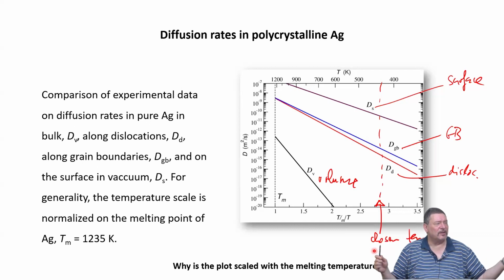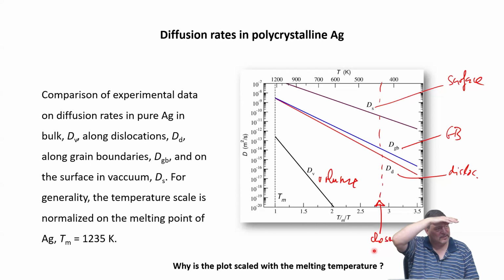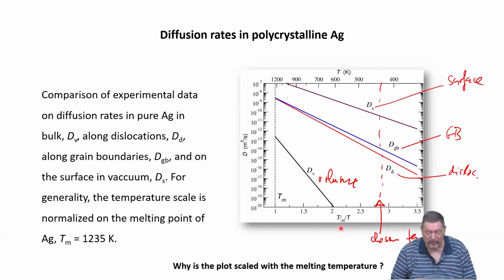The melting temperatures are so hugely different. So if we want to do a diffusion measurement in tungsten, tin is already in the liquid state and maybe is evaporating already a lot, right? But on the same homologous scale, half melting temperature, we can still compare. And this is why it's very meaningful to always plot diffusion coefficients also on a homologous scale, because that will tell you if the order of magnitude of diffusion coefficients at certain homologous temperatures is reasonable.